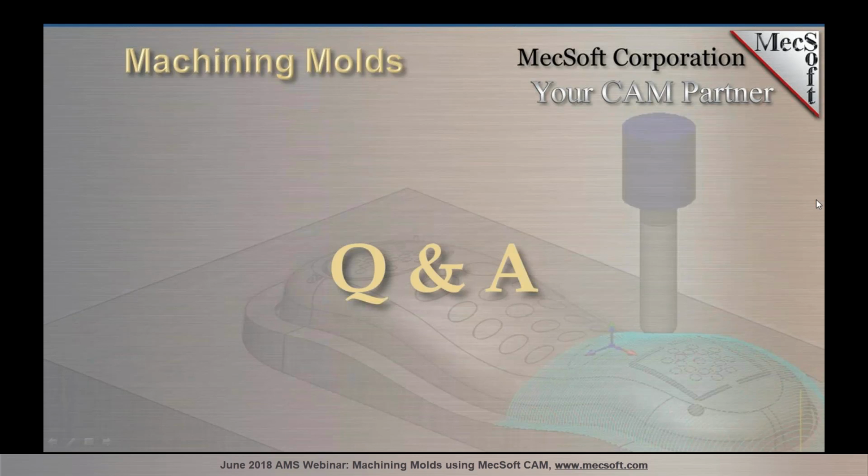Yeah. So for the alignment, I used reamed holes, and what I did is when I modeled it before I split the two halves, I made a hole going through both of them, so I knew that they were going to be in the exact same spot. And then again, I used reamed holes for those. So what I'll do is we'll take a dowel pin, put the two pieces together, and then press fit the dowel pin between both of them.